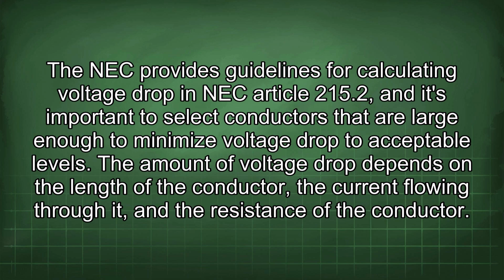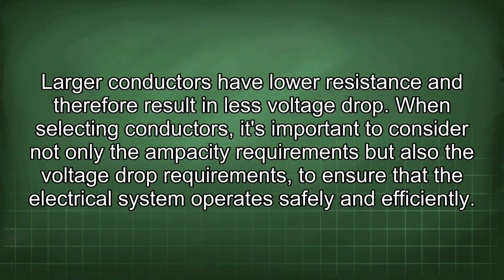The amount of voltage drop depends on the length of the conductor, the current flowing through it, and the resistance of the conductor. Larger conductors have lower resistance and therefore result in less voltage drop. When selecting conductors, it's important to consider not only the ampacity requirements but also the voltage drop requirements to ensure that the electrical system operates safely and efficiently.